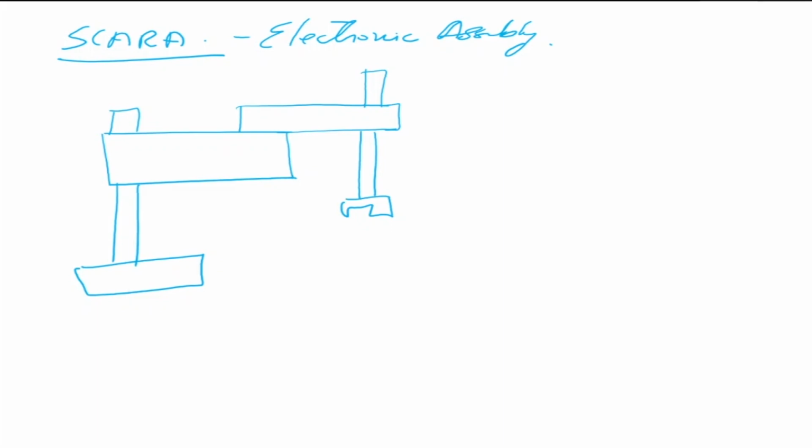Now what we'll do is assign the DH parameter table. First we're going to assign the axes as per DH notation. Then we're going to assign the DH parameter table, make the table, then take each row of the table and make the corresponding frame to frame transformations. So first let's look at how this moves. Where is my first axis? This is my first axis, it's a rotation axis. This is my second axis, which is also a rotation axis. The third axis is a prismatic axis, which is translating, and the fourth axis is a rotation axis.